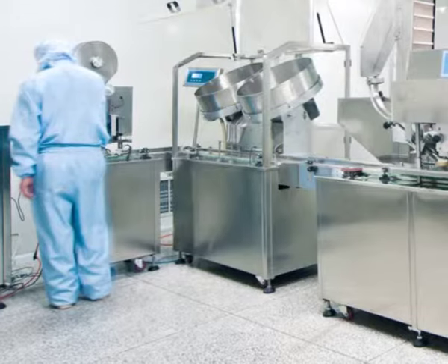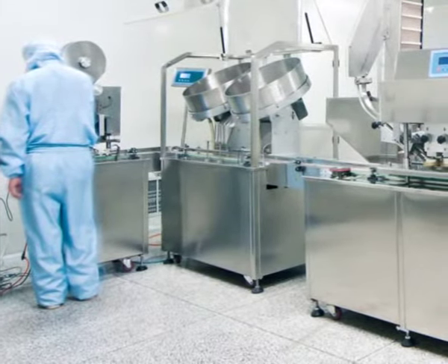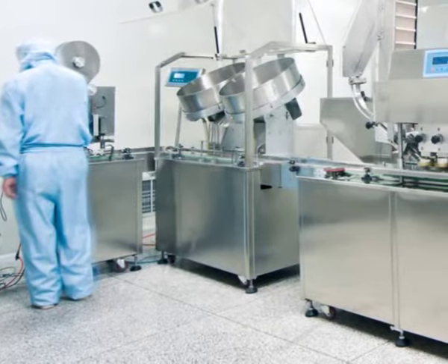Proper clean room design encompasses the entire air distribution system, including the provisions of adequate downstream air returns. In vertical flow rooms, this means the use of low wall air returns around the perimeter of the zone. In horizontal flow applications, it requires the use of air returns at the downstream boundary of the process. The use of ceiling mounted air returns is contradictory to proper clean room system design.